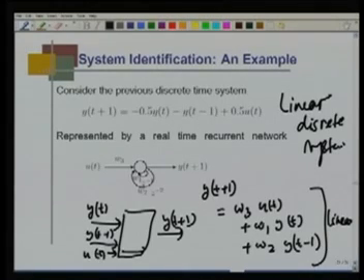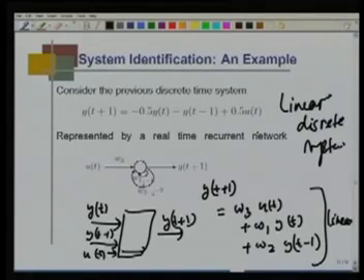What I know is that I can generate data from this particular mathematical model. I can use my MATLAB or C language, whatever computing program I can use, and generate u t, which is a random number, say between 0 to 1, and then I compute what is y1 given u0, u1, u2, u3, u4. So, then corresponding what is y1, y2, y3, y4, y5 and so on.